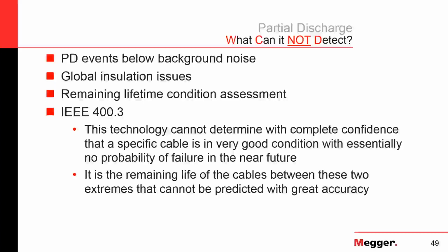It's difficult to give a remaining lifetime assessment with partial discharge. There's certain red flags that we can say, but it's very difficult to say this cable is going to be good for the next year or 6 months or something. It's more of a threshold, this cable is in good shape or this cable is in bad shape.